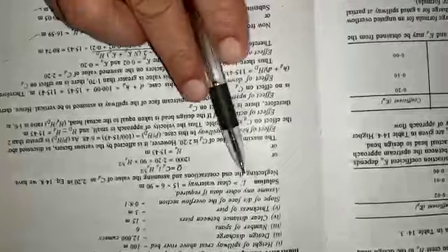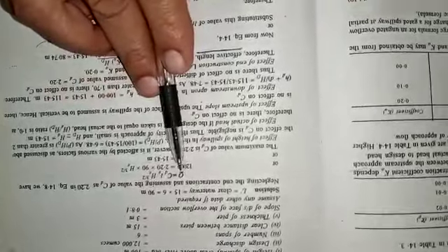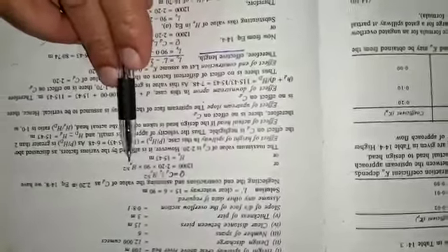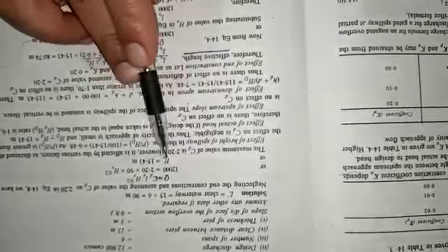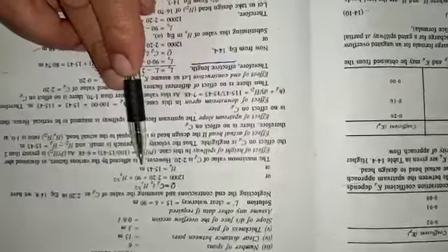Now, assuming this L dash as the effective length of the spillway, and also assuming the CD, that is the coefficient of discharge, C, as 2.2, and from the given discharge, we will calculate the head HE over the spillway, which comes out to be HE equal to 15.43 meters.